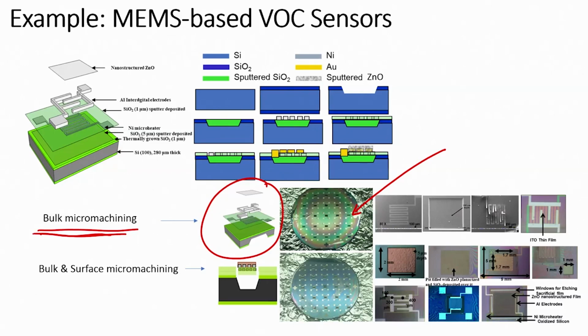If you see this particular figure, on the oxidized silicon substrate is a blown up diagram. The first structure is a heater. So, we have here the heater, you can see an SEM image of a heater. On the back side you can see this diaphragm, right, this etching that we have created.